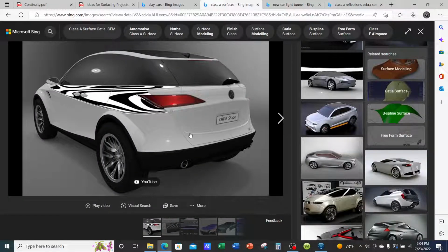So as I mentioned earlier, if you work for a studio department, once you've created the exterior surfaces in Alias or Catia or another software, you can turn on the options, right? As I showed earlier, how to turn on zebra stripes or lighting to reflect off of the surface. And they can tell the decision makers, the supervisors, managers, they can tell if you have a nice clean surface by the way the zebra stripes flow. They want to see nice flows. It's okay if it zigzags as long as the stripes don't break from each other. They don't disconnect or there's a break.